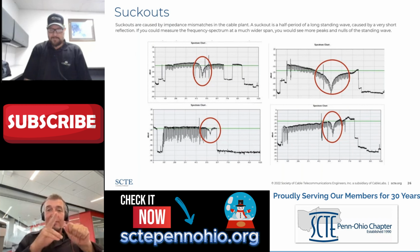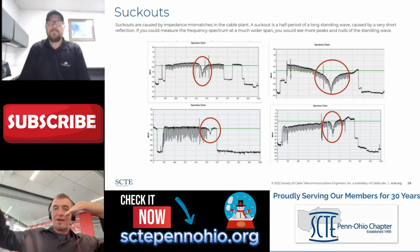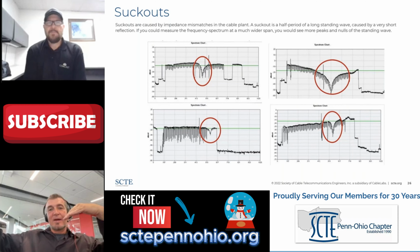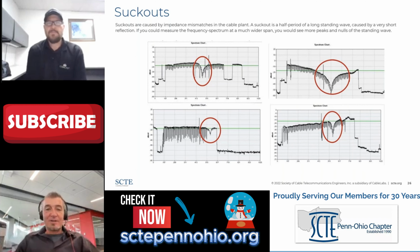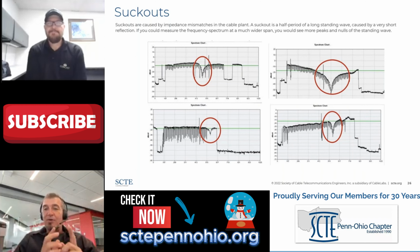And sooner or later, when you cut that cable short enough and create a microreflection, it results in a standing wave where the second incident of that wave is so far out of the spectrum analyzer you can't actually see it. So what you're looking at in this upper left-hand corner is half of a period of a standing wave. That's right. If we did the math, in order for it to result in a suckout in 1 gigahertz of visual spectrum, the reflection mechanism has to be 6 inches or less.